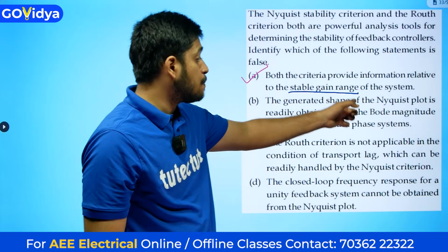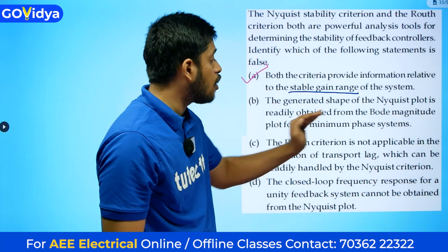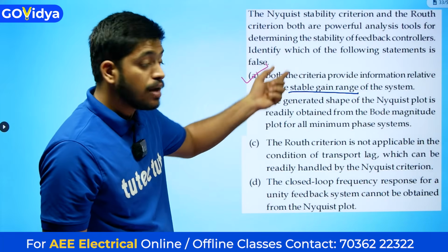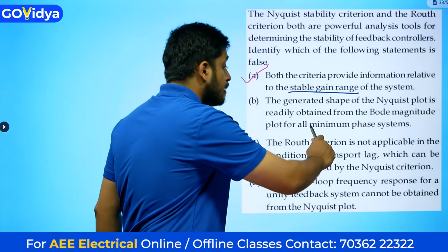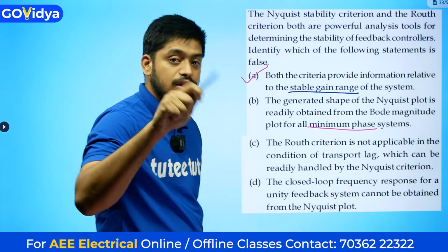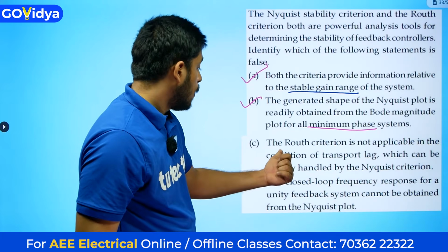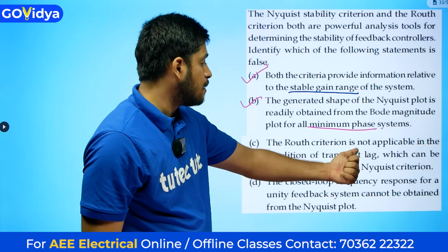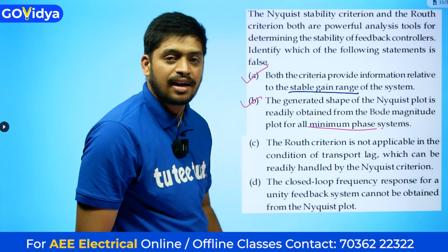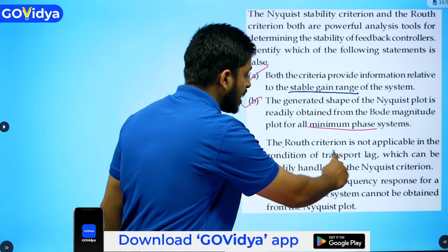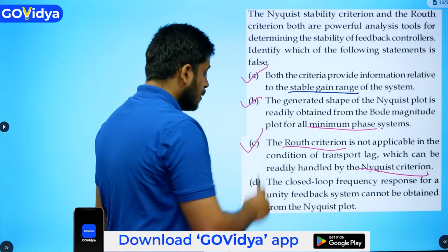The generated shape of Nyquist plot is readily obtained from Bode magnitude plot for all minimum phase systems. Yes, from the Bode magnitude plot, we can find the Nyquist plot for only minimum phase systems. When the system is stable, then we can find the Nyquist plot from Bode plot also. This is also the right answer. The Routh criteria is not applicable in the condition of transport lag, which can be readily handled by Nyquist criteria. Exactly. This is only the limitation of Routh criteria, which will be handled by Nyquist criteria. This is also the right option only.